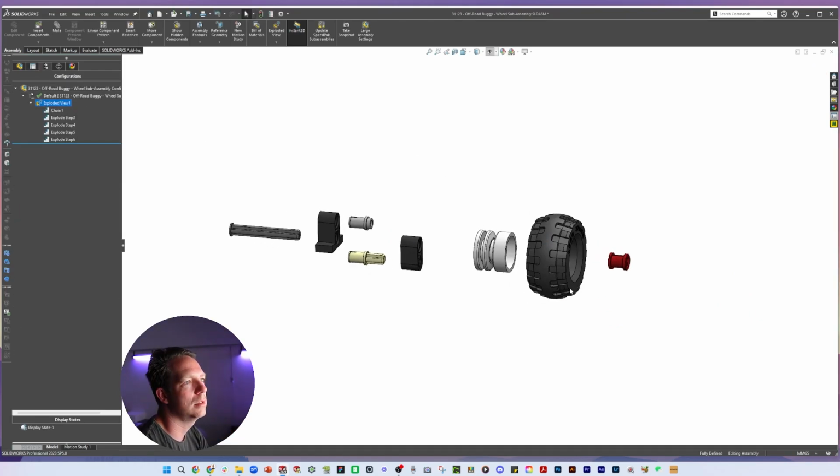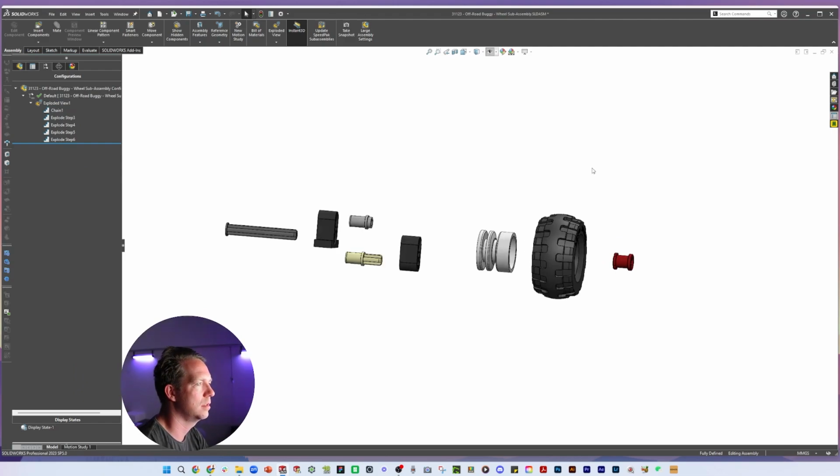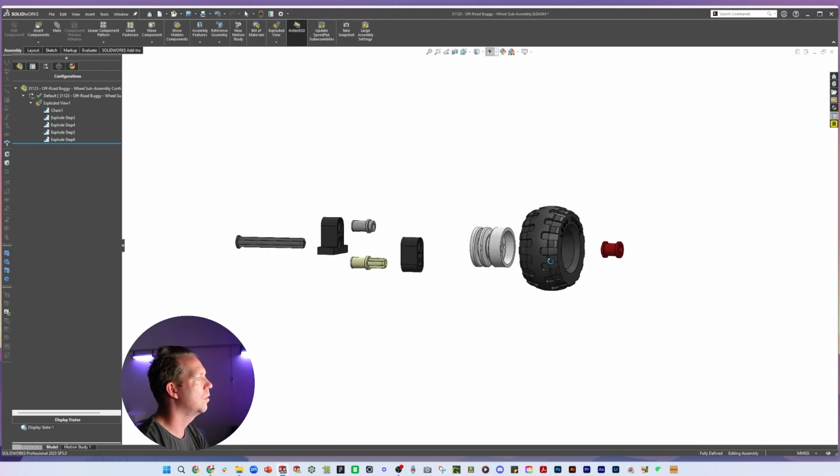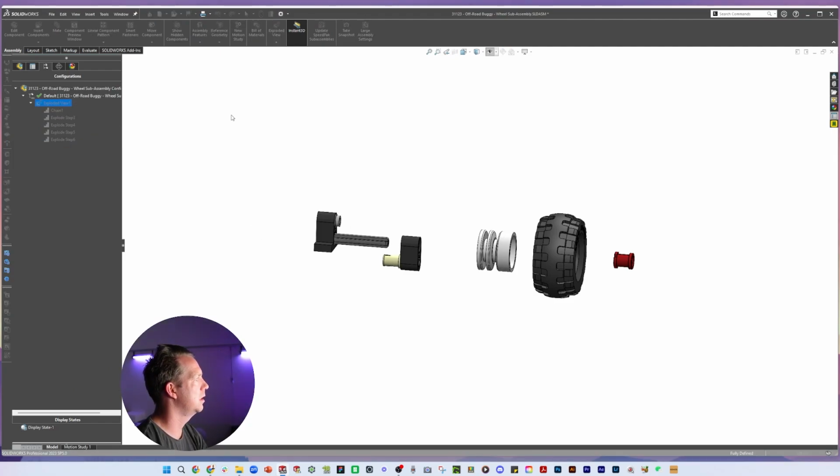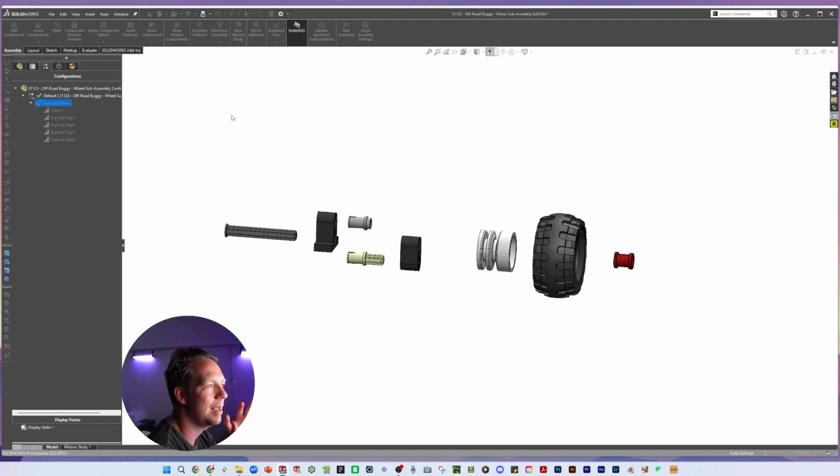So here, what I'm about to show you is, let's stop for a second to test this audio. It seems a bit jumpy. All right, so what I'm going to show you now is just a sample of an animated collapse. This is just automatic, but it's based on the order that we've got here. So when I click on that exploded view and right click, I can press animate collapse and it's going to animate the collapse and exploded view.